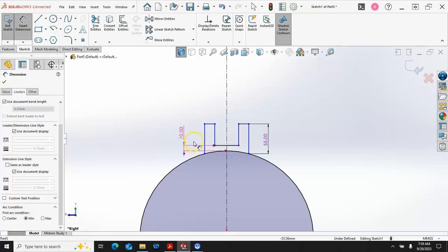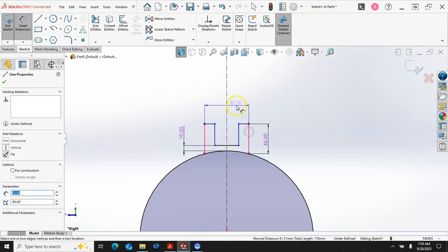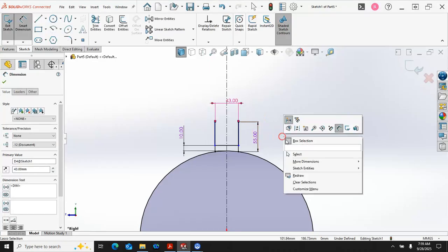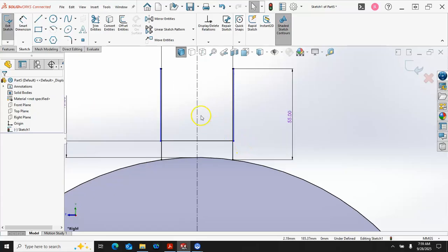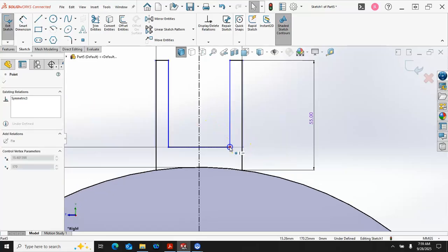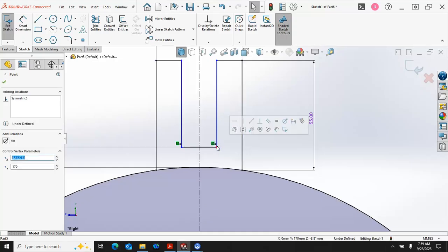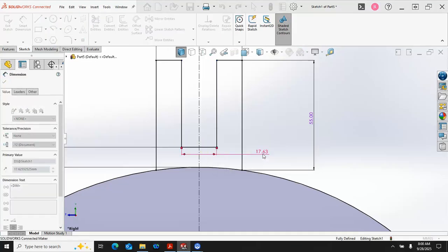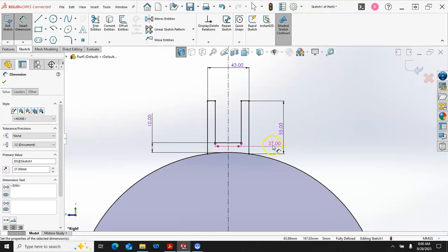What do we have for the width is 43. Oh, that's pretty wild. So let's see if this inverts at all or does anything. Yeah, it did kind of strange. So the result just means that I need to zoom up, drag one of those blue points to where we get a better solution. So let's see, we have 27 on the width. We'll grab the smart dimension, go 27. Again, we should just be in the habit of pick your object or objects, place the dimension, enter the value.